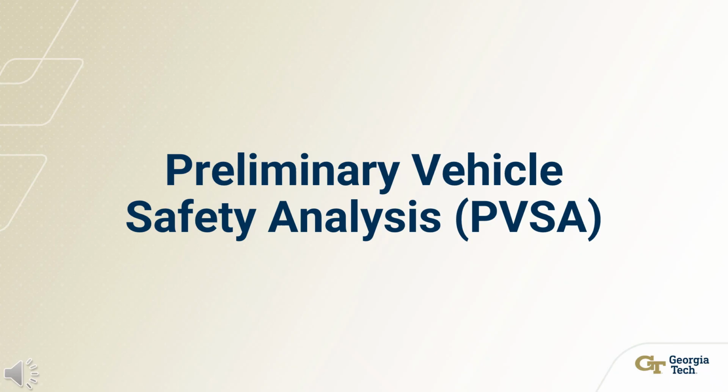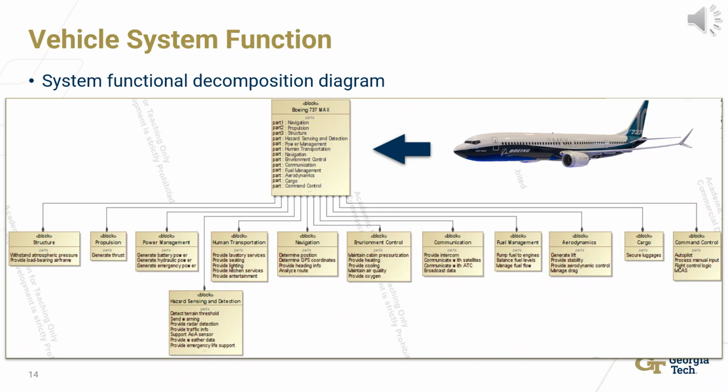Our approach aligns with Aerospace Industry Standard ARP 4761A, which starts by defining aircraft-level functions, mapping their interactions, and identifying critical hazards, which then allows us to develop our system fault trees, identify assurance levels, and perform probabilistic risk assessments. You are looking at the block definition diagram.